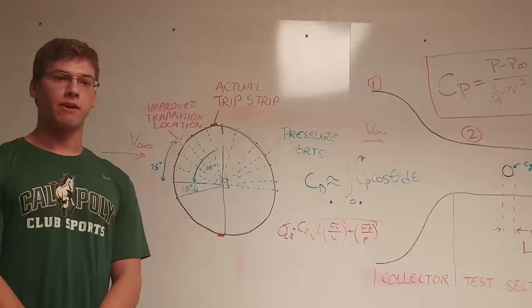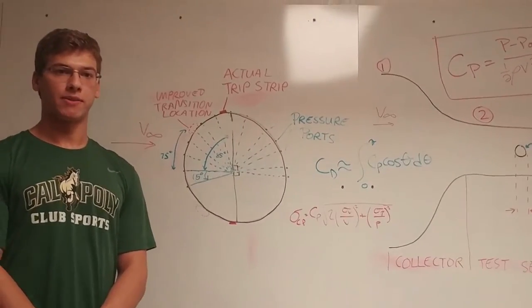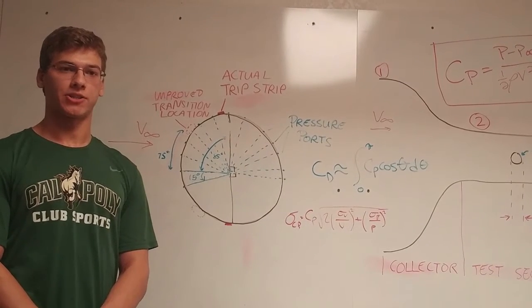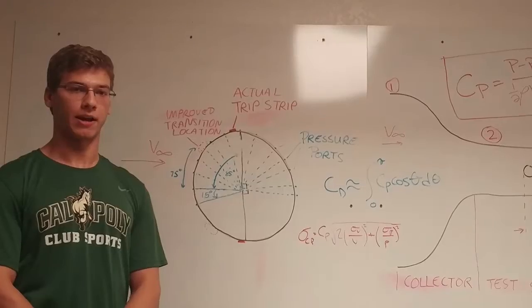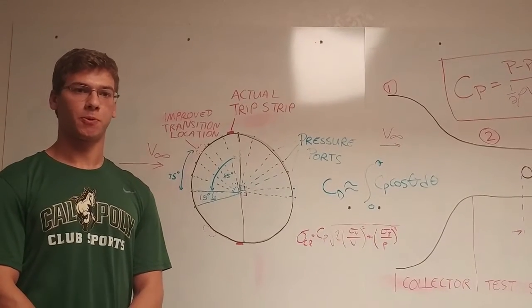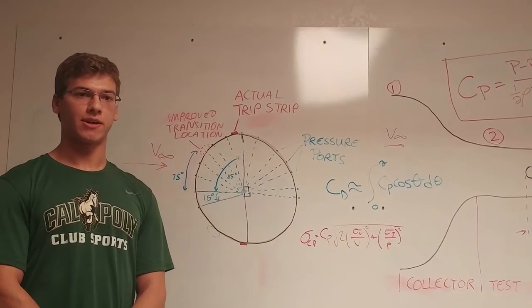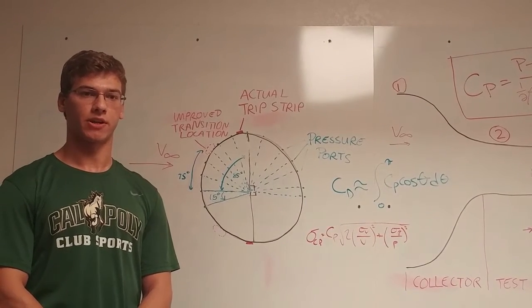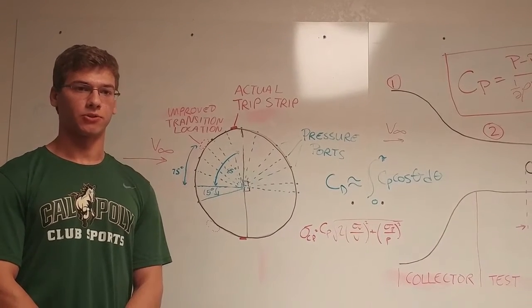method. Essentially, we have 24 pressure measurements, where pressure is force over area. So if we multiply these pressures by an area, we can determine a force. The only extra consideration here is that we need to take only the component of force in the streamwise direction for drag. As such, we took pressure at each port and multiplied by the cosine of the respective angle. Next, each streamwise pressure was multiplied by 1/24 of the total lateral cylinder surface area, 2 pi RL. And then these drag portions were all added up for a total drag.